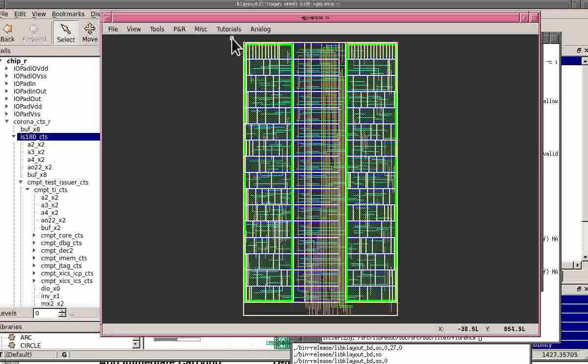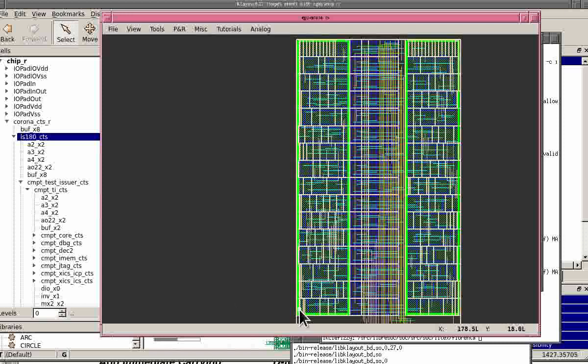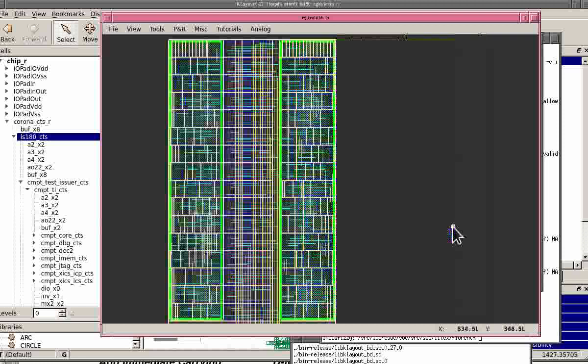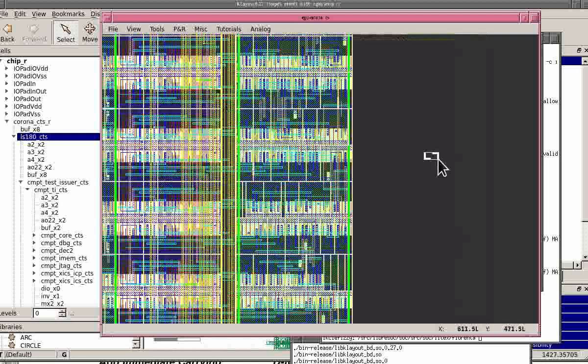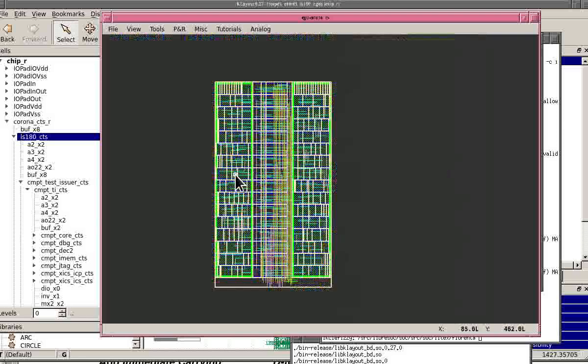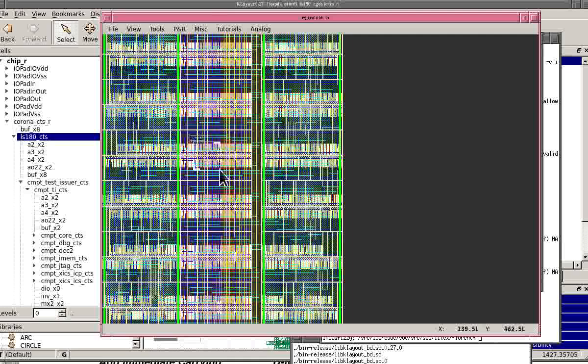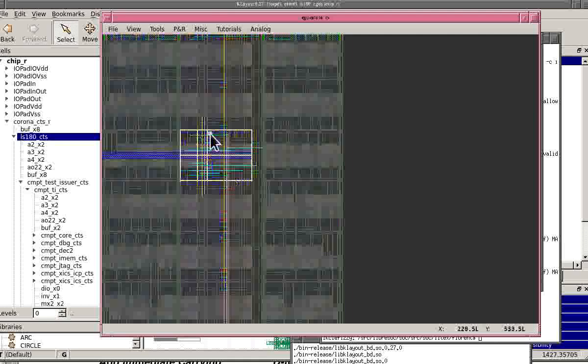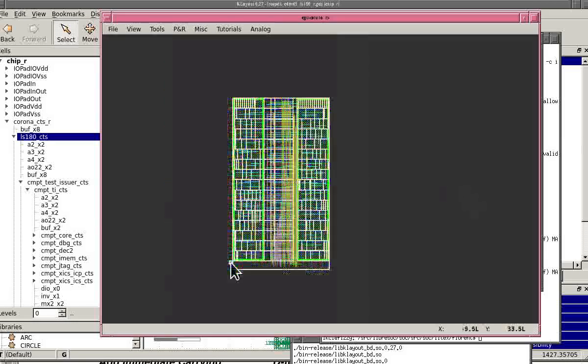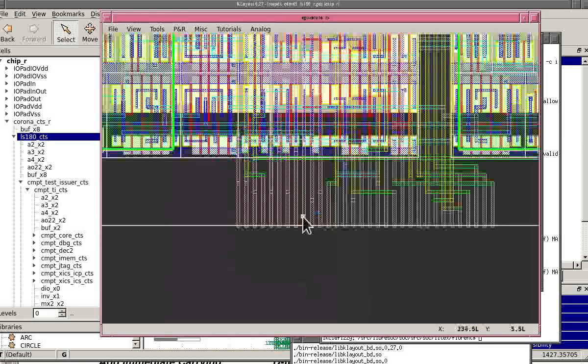Now, in this particular program, and this is a beautiful thing about Coriolis 2, I did a manual place of the adder on the left side and a manual place of the subtractor on the right. And then I did a manual place on the individual components of the cells in the muxes, and from there I asked Coriolis to handle the routing.